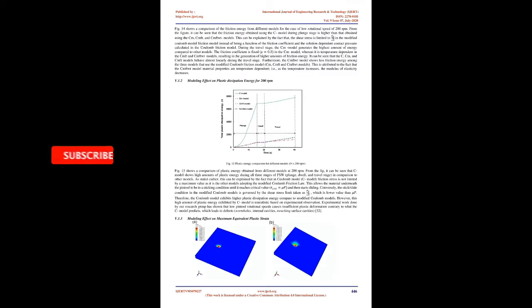Temperature validation along longitudinal direction. Fig 12 shows the comparison for temperature field at the thermocouple location number 3 in the direction of weld for different models. The peak temperature at location 3 is 362 °C, 369.09 °C, 361 °C, 373.41 °C, and 365 °C for C, CM, CMFT, and CMFTWT models and the experiment, respectively.